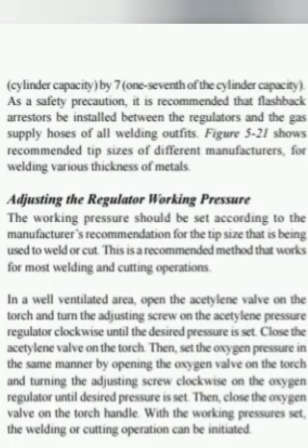As a safety precaution, it is recommended that flashback arresters be installed between the regulators and the gas supply hoses of all welding outfits. Figure 521 shows recommended tip sizes of different manufacturers for welding various thickness of metals.